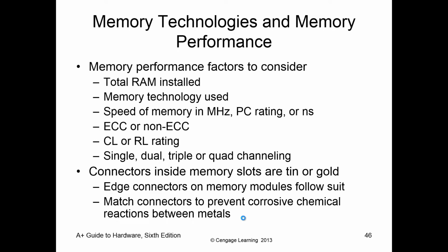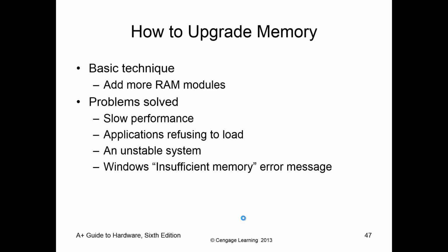Also bear in mind that our memory connectors are gold, typically, and be careful, you don't want to touch them, because again, the oils on your fingers are corrosive and could damage the memory module. Adding memory is pretty straightforward. You check the documentation, you see what's supported, you verify there's an open slot, you put new memory in.